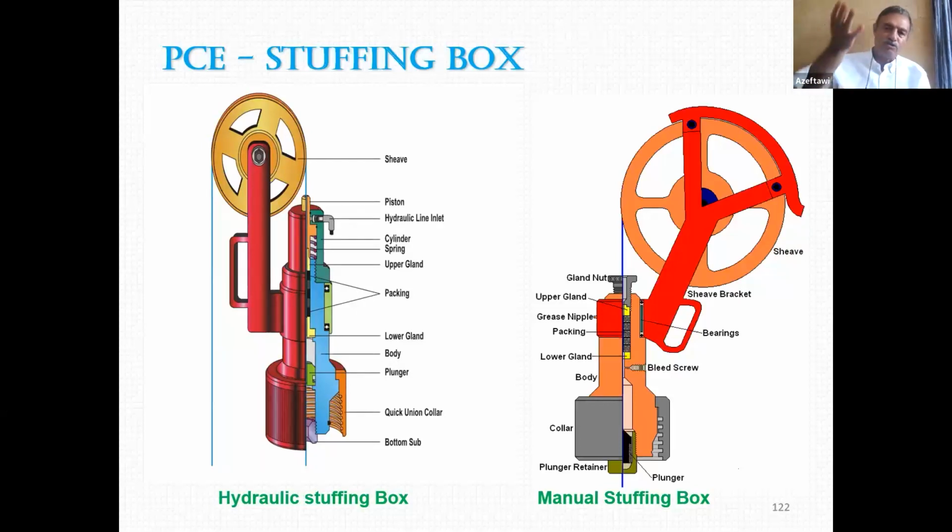And you are pulling out of the hole and you lost your tools. The wire is cut, you lost the tools. Now you are getting out of the hole with the wire line free. That means that when you reach the surface, nothing will stop you from getting out of the stuffing box. What comes out after that? It's a blowout, hydrocarbons.